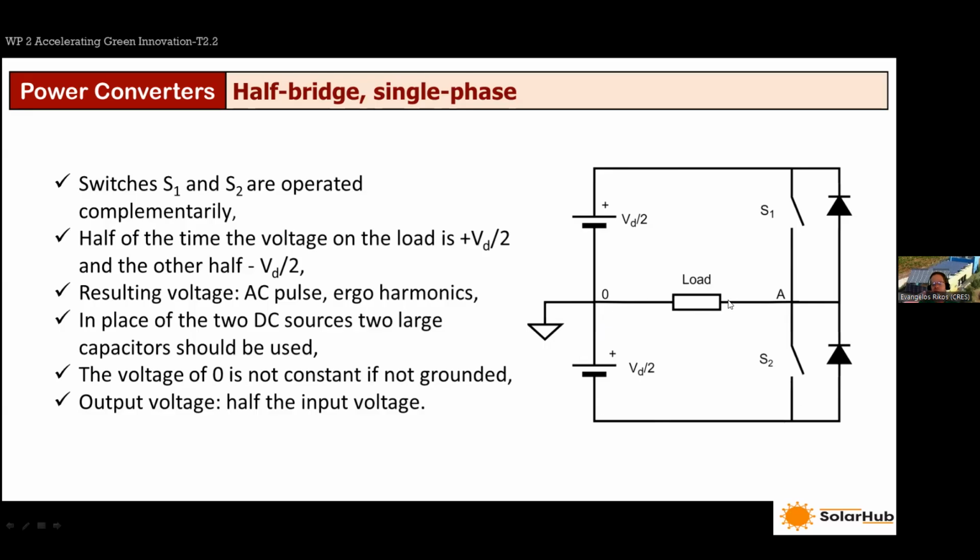And this means that we have managed to reverse the current. This current reversion through the load is what is the AC generation in principle. It's not the sinusoidal waveform itself. It's that we have achieved a current flow that is alternating. There are some disadvantages of this very simple topology, however. The voltage level is rather low as opposed to the full DC level here. Instead of VD, we always have half of VD on the load.